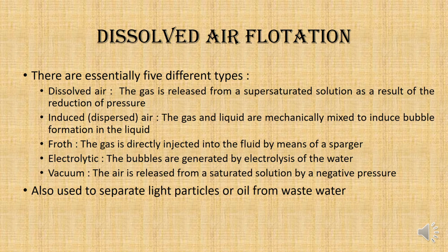In the air flotation process, the air or bubbles are introduced by one of these five processes. Either there is a reduction of pressure in the solution, and the gas inside the solution gets dispersed; or gas and liquid are mechanically mixed together, churned together to induce bubble formation; or the gas is directly injected into the fluid by means of a sparger, which occurs in bioreactors very often.